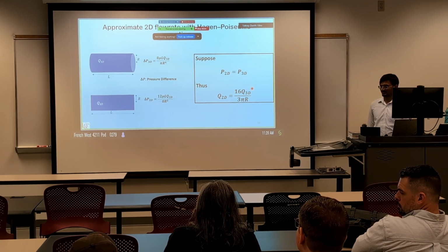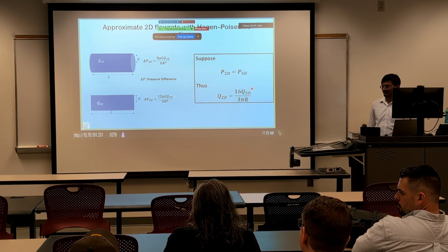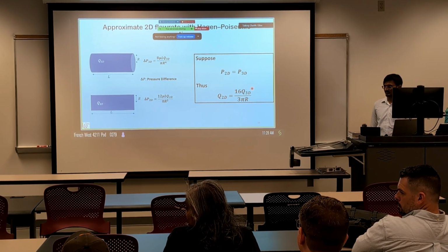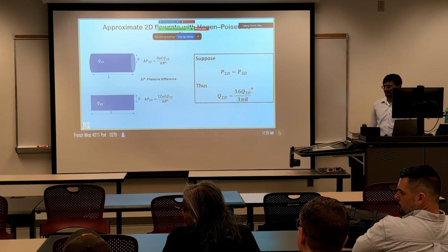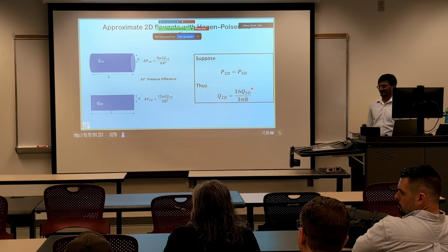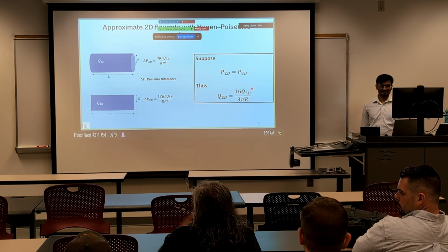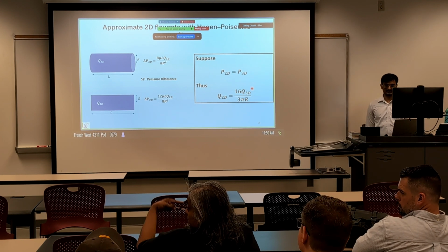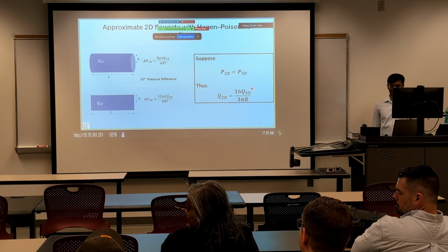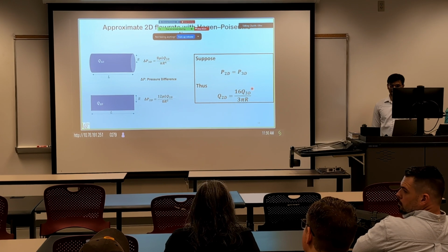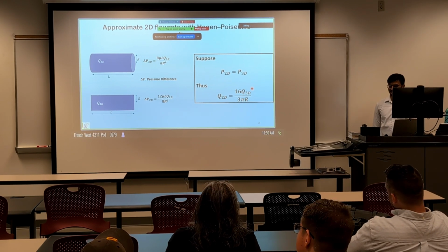But when you compute the actual pressure drop, it turns out to just be that constant. It does depend on how high it is and how long it is. But if you took any vertical slice, you have the same velocity profile. If you took any horizontal slice, you have the same pressure profile. But the velocity profile should change with the vertical distance, because of the slip condition. Yeah, it is still parabolic.